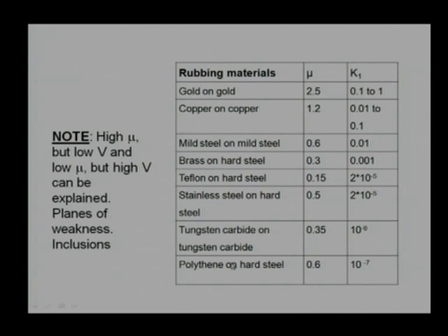And what we are adding in this slide is a plane of weakness. If the material has planes which are weaker than the surfaces, then wear rate will be high, or if there are inclusions in the material, wear rate will be very high. We will discuss this later when we cover one case study in the next lecture, how inclusions can create more problems.